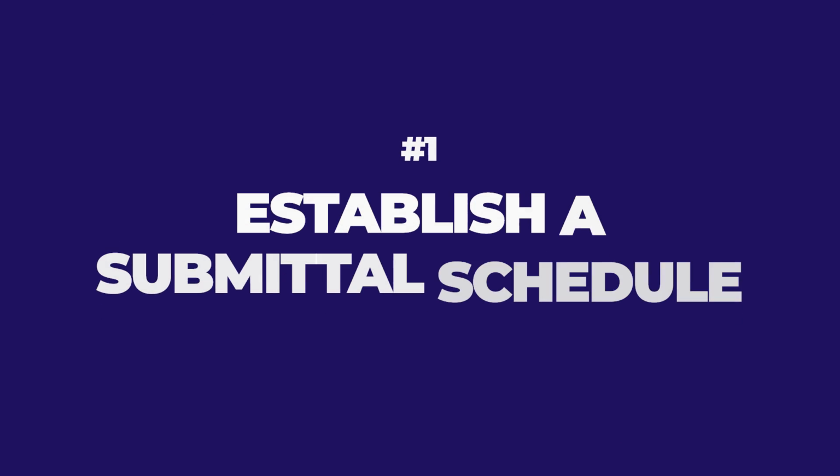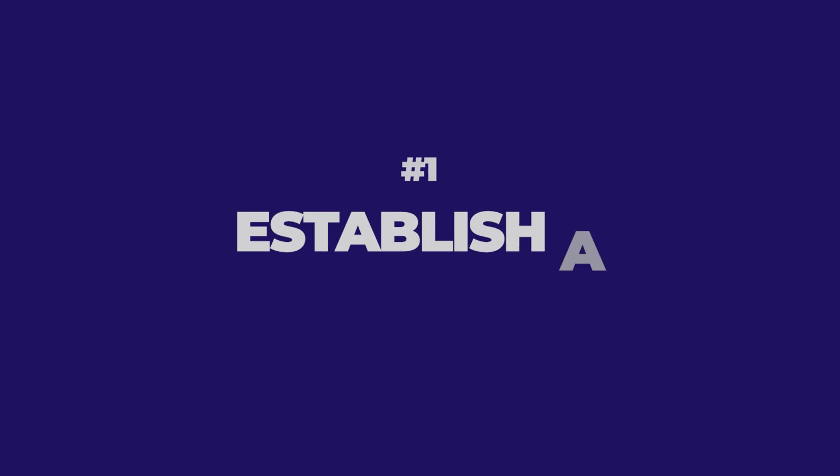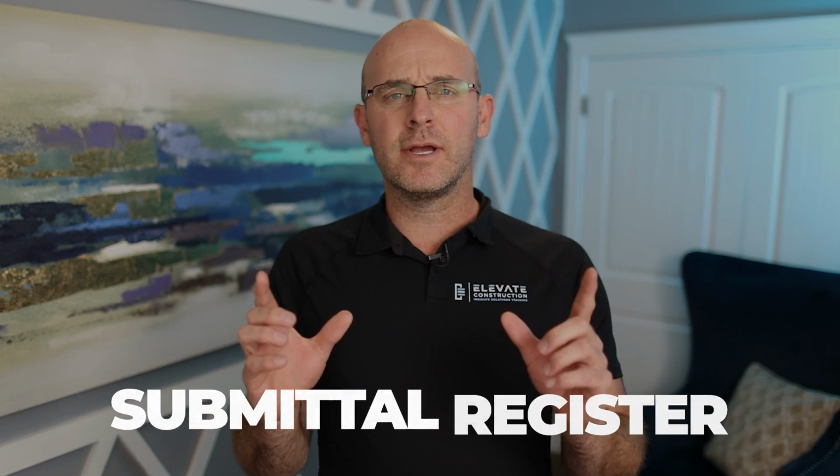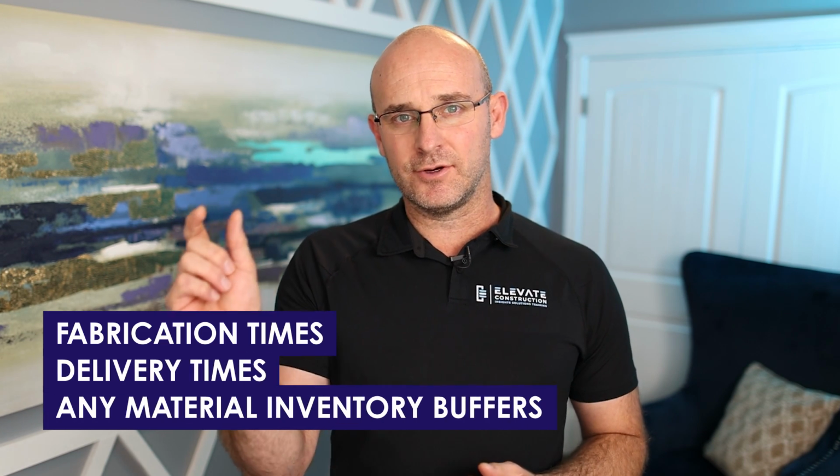Number one, establish a submittal schedule. Develop a clear, detailed schedule for when you want to review and submit submittals. Now, this is typically called a submittal register. I highly recommend that you loop this into a broader log or schedule as part of your overall procurement effort, which also includes the fabrication times, the delivery times, and any material inventory buffers, and manages the entire process together.